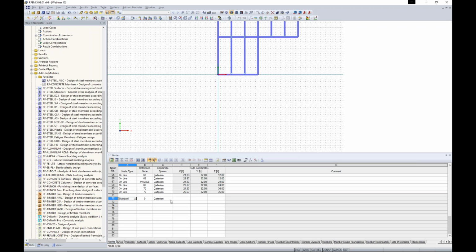I'm going to create my first node, and all I need to do is to specify the specific coordinates that I'd like to apply this node. So we'll start with -23 in the x, -25 in the y, and z will be 12. And then simply using my down arrow, I'll create my second node at 39, -3, 12, and lastly, my third node will be at 15, -45, and 12.